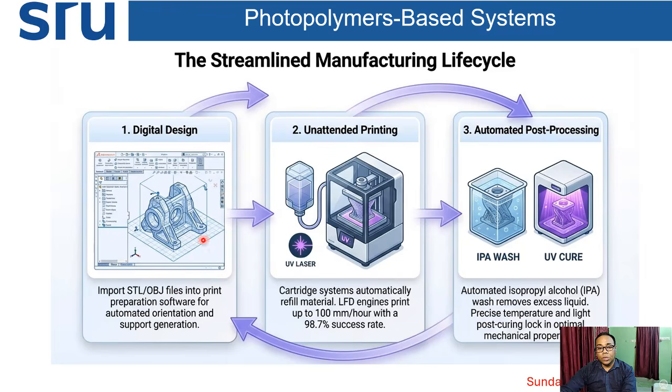Means you have to save your file in STL file format, then only that STL file format will be acceptable for the slicing operation. In that slicing operation, layer upon layer slicing of the part or design will be done, so that the development of the product will also take place layer upon layer. Whatever layer thickness is set in the slicing operation, that layer with that thickness only will be printed at that layer height.